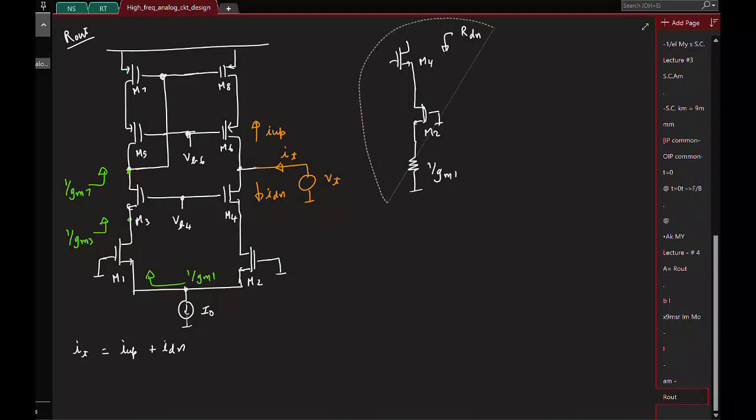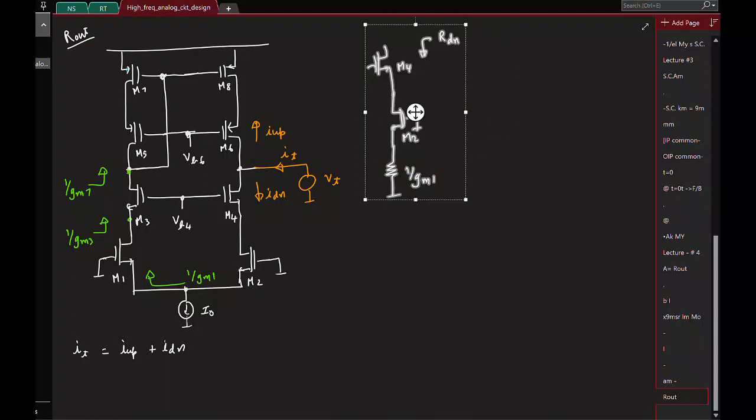If you think about it, what we have is basically a triple cascode. This portion here is the normal cascode, what we had for the earlier op-amp also. If this has an equivalent resistance of some R prime, what is this R prime? That is looking here.